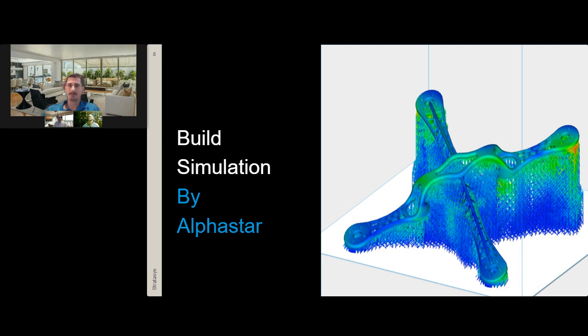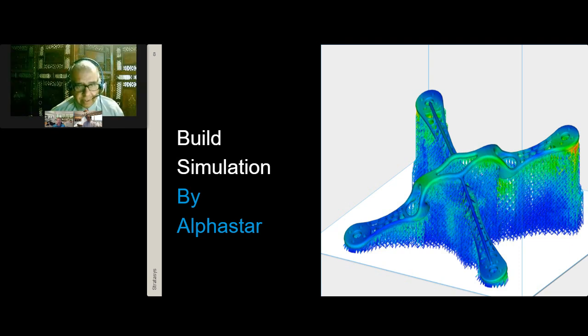Yeah, I would just add first and foremost that WAM feature is a really great tool. Really, really nice capability. You guys did your homework well on that one. Where we would come in is, again, more on the thermomechanical analysis. So not only are you predicting the build quality, but you're predicting based on the defects that arise, the process, the G-code, all that information, thermal model, thermal distribution. When you kick in the thermomechanical structural stuff, you can see and predict distortions, and you can understand where is the shrinkage, where is the warpage, what's going on, how is that impacting the build, which is what you guys are doing already, which is pretty cool.